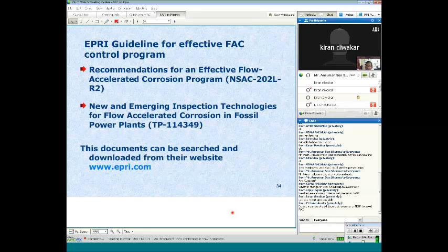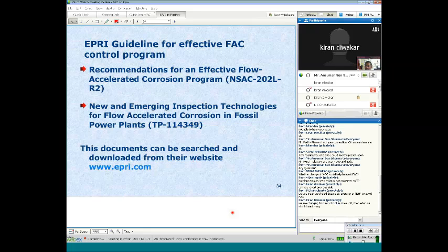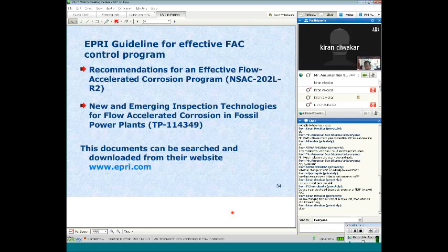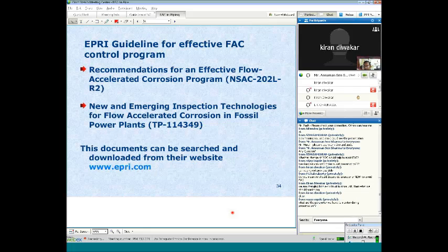Mr. Chakravarti asks, do you mean we should discard the deaerator or N2H4 to avoid FAC? No. Deaerator, no. N2H4, yes. In case of all ferrous metallurgy, AVT(O), if you are reverting to AVT(O), then you cannot use N2H4.